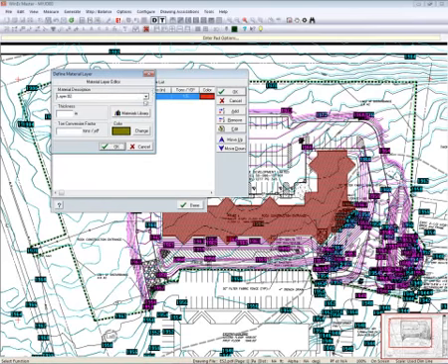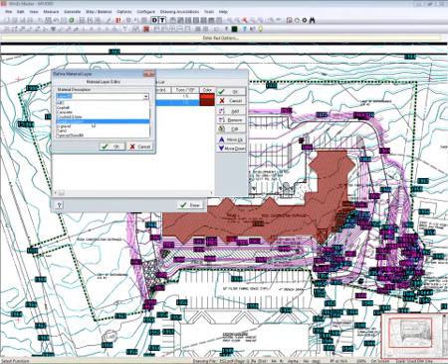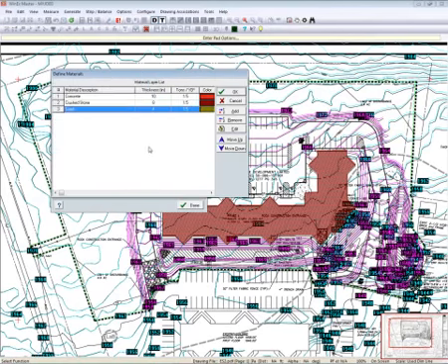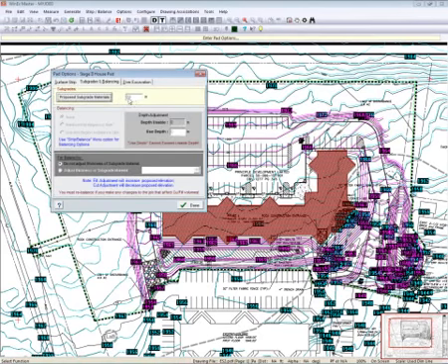And I'll say OK. And maybe we got some crushed stone. And we'll put 8 inches of crushed stone in. And we'll do one more. Let's say we've got some sand. And now I'll cancel out of this. So I've got the 22 inches of subgrades. I'll click OK. The software verifies that. But now I've got a pad that all the way around the pad, I need to get my crew in, and I need to drop some equipment in.